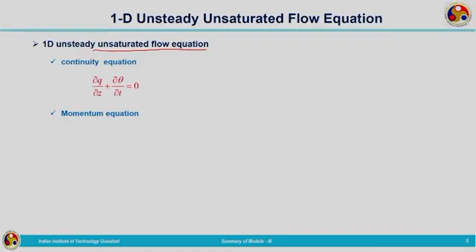The continuity equation was given by this partial differential equation, and for the momentum equation we considered Darcy's law, given by Q is equal to K S_f. Corresponding to the S_f slope, we substituted the energy causing the flow, and finally the momentum equation was found to be in this form, having the terms soil water diffusivity, soil moisture content